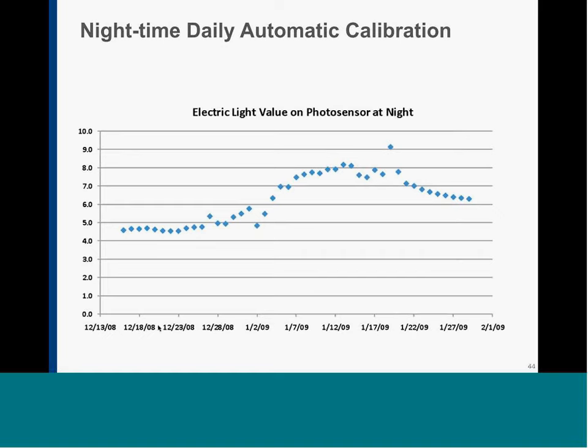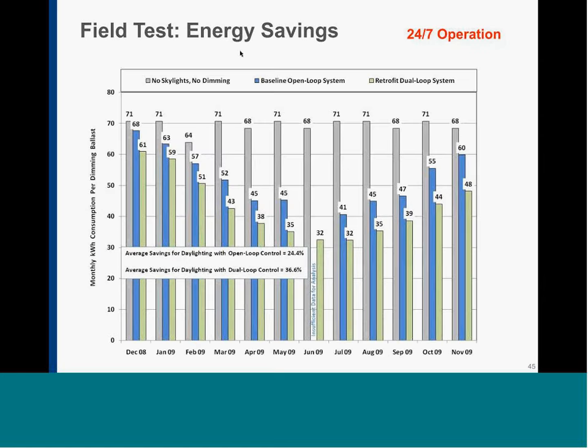Here now, the energy savings. On this plot, we have the months down there, reported monthly. Keep in mind that Walmart operates 24/7, which means that for the bottom half of this plot, it's impossible to save. There are 3 bars for every month. One is without skylights and without dimming, like what if we left the electric lighting on continuously 24/7? And you can see that the wattage, this is per luminaire, changes only per month.